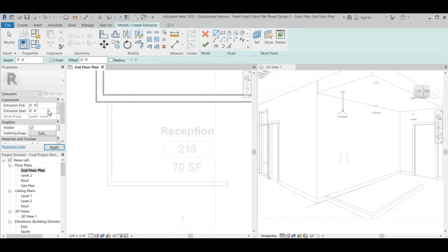So from the 0 up, what is the wall for the worktop? So from the floor level, what is our height of the wall? And so if the finished height of the desk is 30 inches and that countertop is 1.5 inches, then we need to subtract 1.5 inches from 30 inches. So our finished height from 0 would be 28.5 inches. And then hit apply. Now we want our wall to extend out from the toe kick. So we're going to come about 1 inch out from the toe kick area. So type in 1 inch.